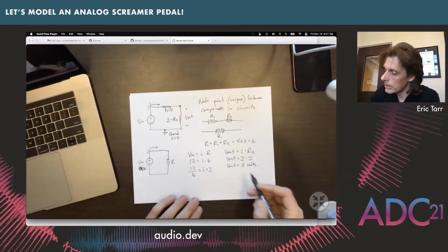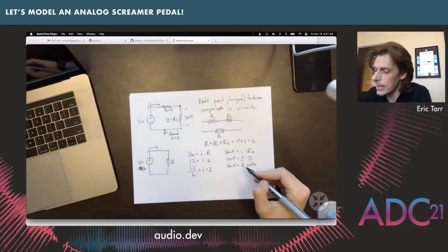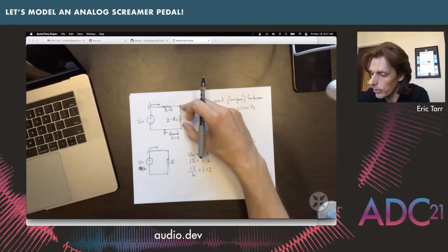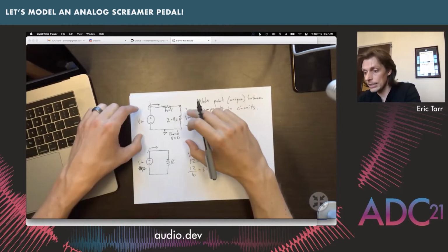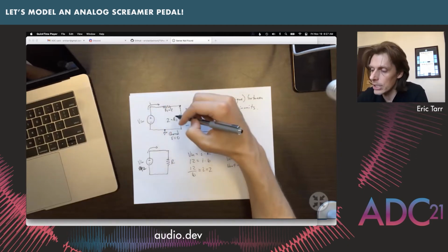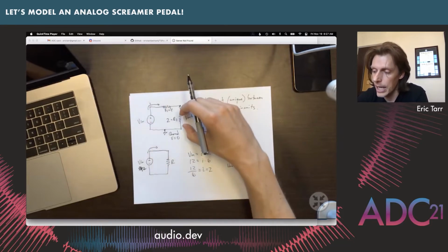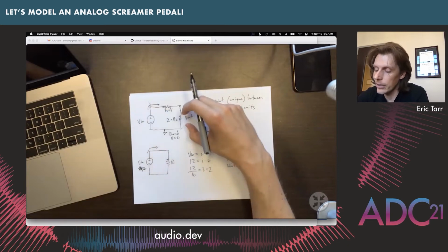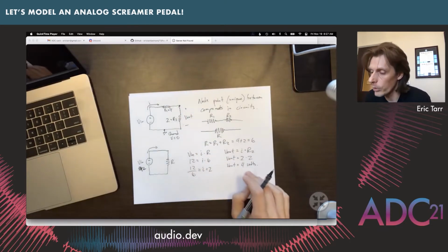Okay, so we started out with an input voltage of 12, just some arbitrary number, and we go through some resistors, and now we have a voltage at this section of our circuit with a value of 4 volts. This type of circuit is actually a passive attenuator that takes some input voltage and reduces it. If this is the amplitude of a signal going in, we can figure out that there will be less of that signal over here. The amplitude is going to be reduced at our output. So that's one way that it can be calculated.